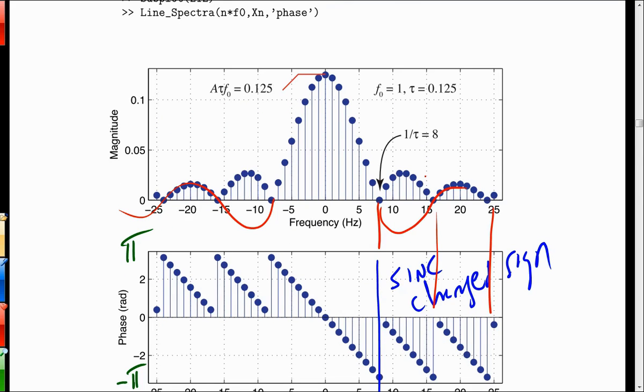Later on, when we talk about modulators, which maybe I'll get to the modulation theorem today, the fact that that spectrum is centered at 0, if we multiply, we'll learn that if we multiply the pulse train times a high frequency carrier, then we'll be placing this whole spectrum up on a high frequency. And so that's where one of the applications of the pulse train comes in, in a simple radar system where you're just going to gate a high frequency carrier on and off with the pulse train. I'll say more about that when I get there, if I remember. Hopefully I'll remember.